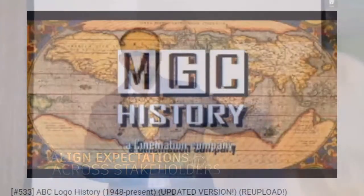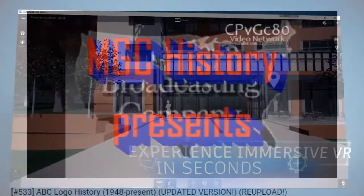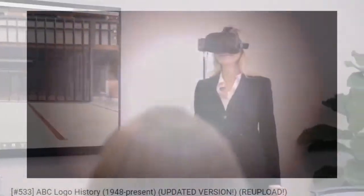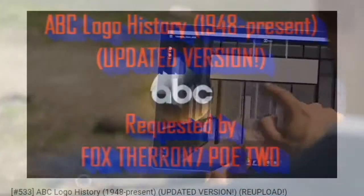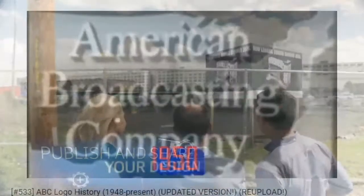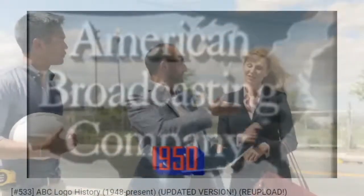And give it what do we got here? Not much. We can make it wood. We can make it wood veneer, wood flooring, maybe. Let's go with some wood flooring just for ha-has. Hit OK. Hit OK. Finish 2 must have a thickness we didn't give it. Let's give this 3/4 of an inch, 0.75. 3/4 of an inch, and hit OK.